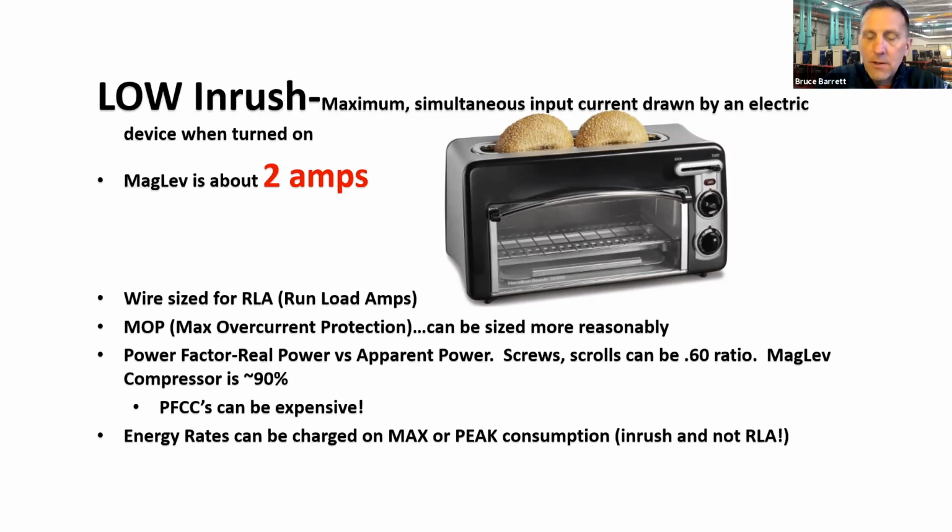A lot of energy companies penalize for peak kW use. You can size your electrical off the run load amps of this compressor and not the inrush. Power factor is very strong, 0.90 or better power factor, standard on all these compressors. So you shouldn't need any external power factor correction capacitors if, for example, a government job might require it.